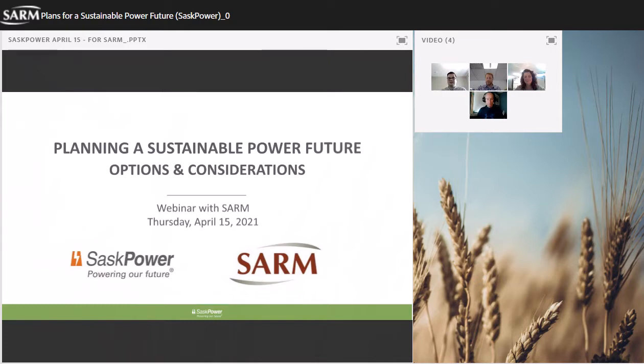The next thing is electricity imports, and I'll just bring up all these little bullets here. I talked about transitioning potentially away from conventional coal, and the challenge with that, as I said, is some of the options we're looking at aren't going to be available by 2030. So if we're looking at SMRs or we're looking at hydrogen storage, they will be available after 2030, hopefully, but they won't be available in time to replace retiring conventional coal. So to avoid having to build large infrastructure like large natural gas facilities just to back up and replace retiring coal, we are looking at increasing the amount of tie lines we have with other jurisdictions to Manitoba, south to the US, and west into Alberta.